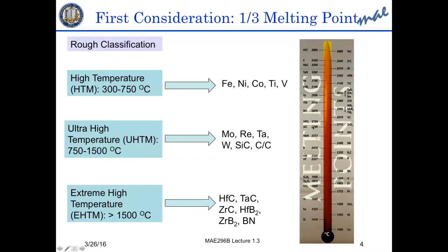And then in addition to this, we have the silicon carbides, 2700 degrees C, and then you get some of the materials that are used for coatings, like iridium, for example, 2400. Boron is a very light metal, and it has a very high melting point, 2300. And that's why when you combine it with nitrogen, you get very tough, high-temperature ceramic boron nitride. Boron nitride, for example, is used in Hall thrusters as an insulating material.